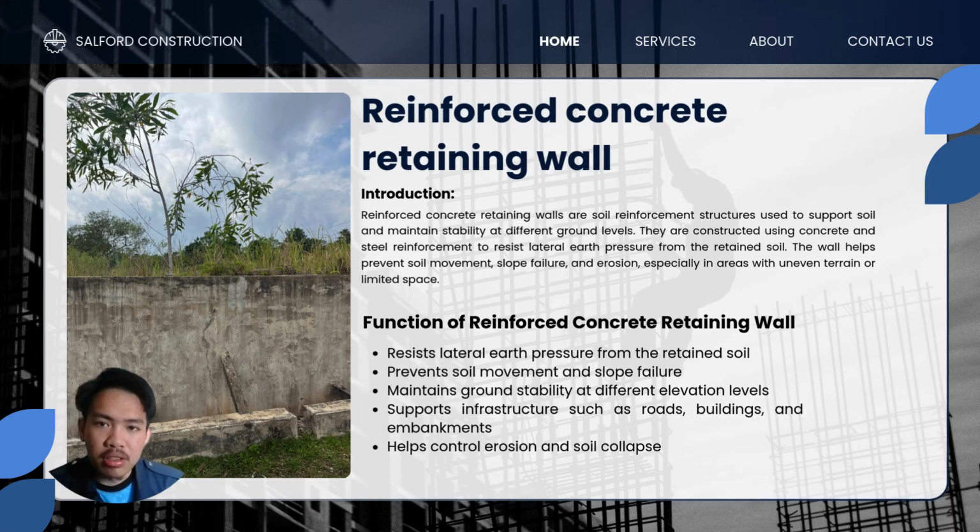The function of the reinforced concrete retaining wall is to resist lateral earth pressure from the retained soil, prevent soil movement and slope failure, maintain ground stability at different elevation levels, support infrastructure such as roads, buildings, and embankments, and help control erosion and soil collapse.